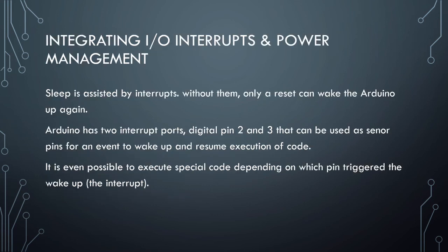One of the ways that we can help reduce the power being used is by integrating some interrupts and a sleep mode. So we can use a sleep mode in a microcontroller that is assisted by interrupts. If you didn't have those interrupts and your microcontroller went into a sleep mode, the only way you could bring it out would be to reset the board. But by using interrupts, we can look for a certain input to bring that microcontroller out of sleep. The most simple example would be a button press. The board would be sleeping to conserve power, and a button press would bring it out of sleep mode. So that negates the need for a reset or anything like that.